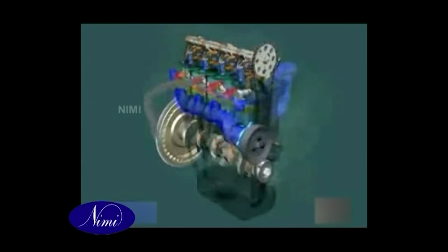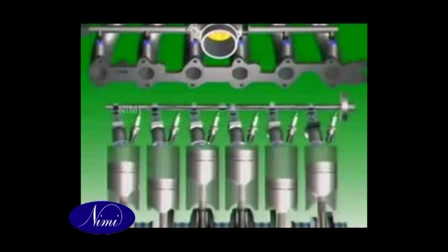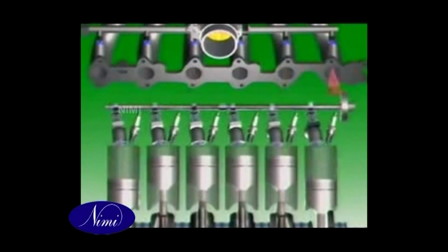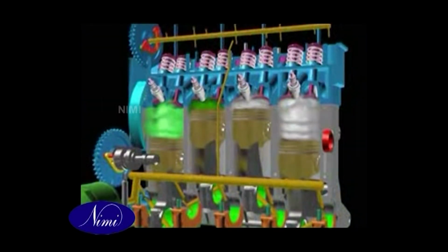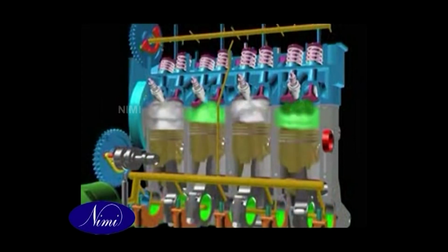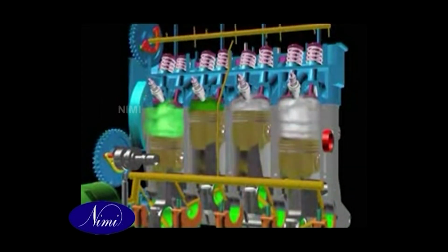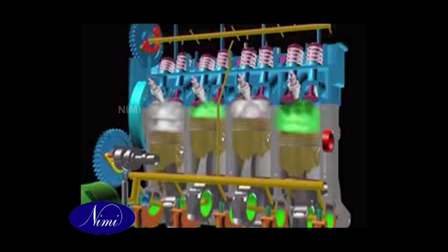Since the power output of a cylinder is controlled by the quantity of fuel injected, the system must be calibrated to ensure that each one of the cylinders receives an equal amount of fuel. Unbalanced fuel supply will cause a variation in the cylinder power output and result in rough running of the engine. Fuel injectors are sensitive and therefore require clean and pure fuel to prevent troubles owing to wear and blockages.